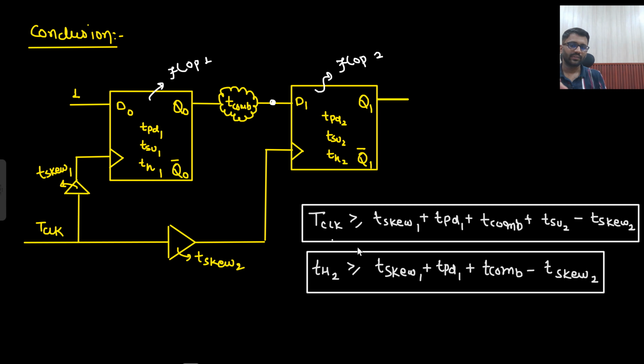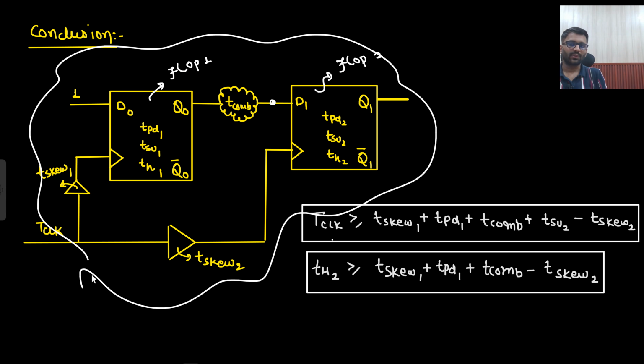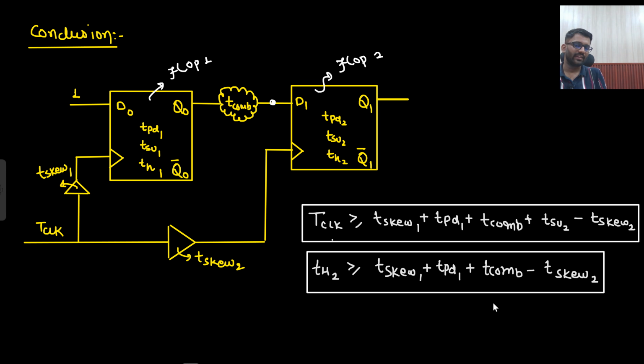So this is how this complex circuit is taught. Usually they will make this diagram and write these things, so people get confused, right? But now we have seen the timing diagram, we have seen the core depth of this concept: going from here to here, we need a setup margin, and since my clock is more delayed, I will subtract this. And for hold time, I need all the delays but no setup margin there. My clock trigger should be behind that, so that much margin I need.